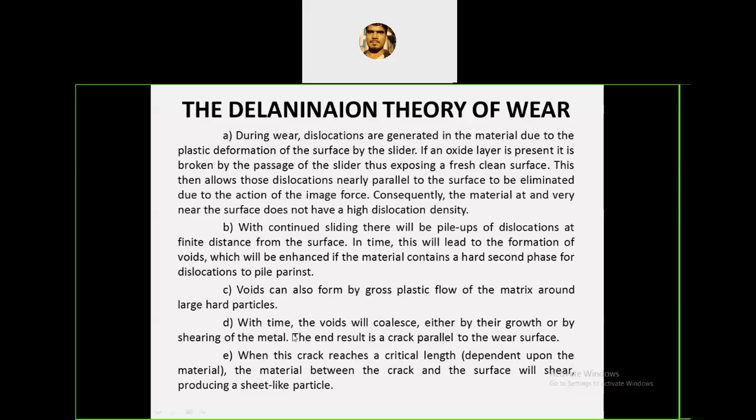If it is a plastic deformation, we have to reduce the load and take whatever necessary action; that will reduce the weight. If there are small voids and you avoid those voids, it will reduce the crack formation. If there is a crack, we can take some preventions and reduce the failure. If the sublayer has already formed, we cannot do anything. It ultimately wears off, with loss of material. Clear? That is the delamination theory of wear.